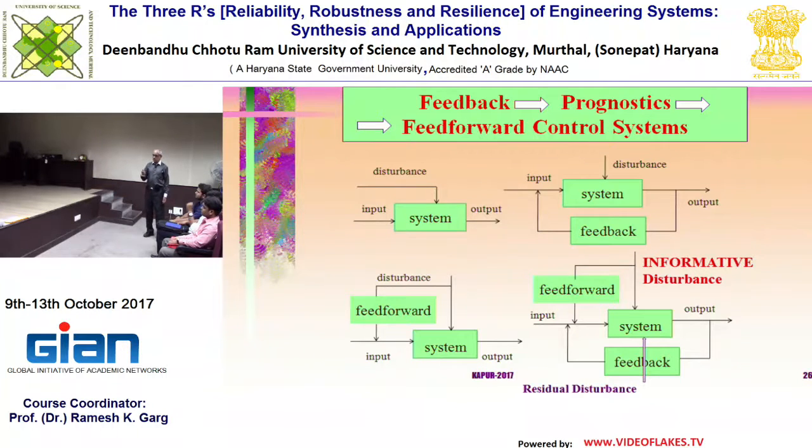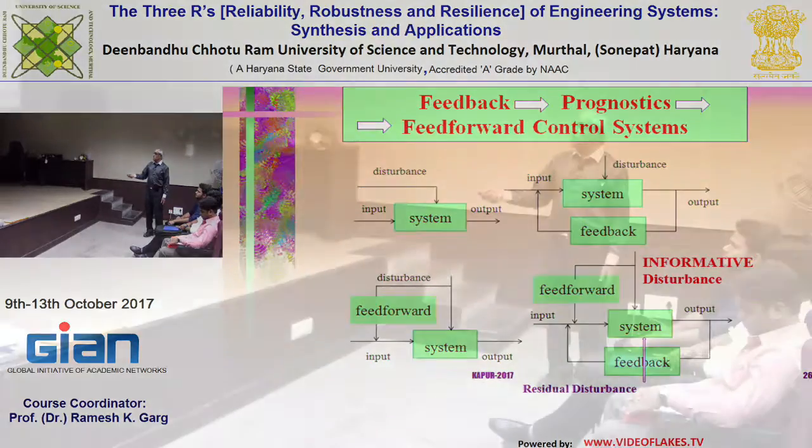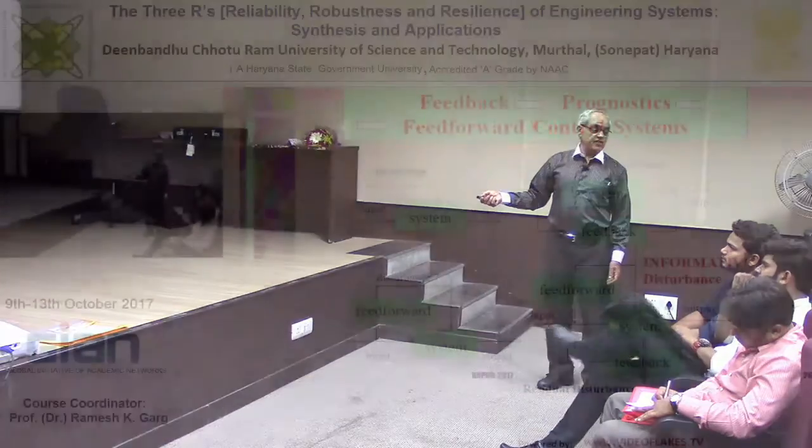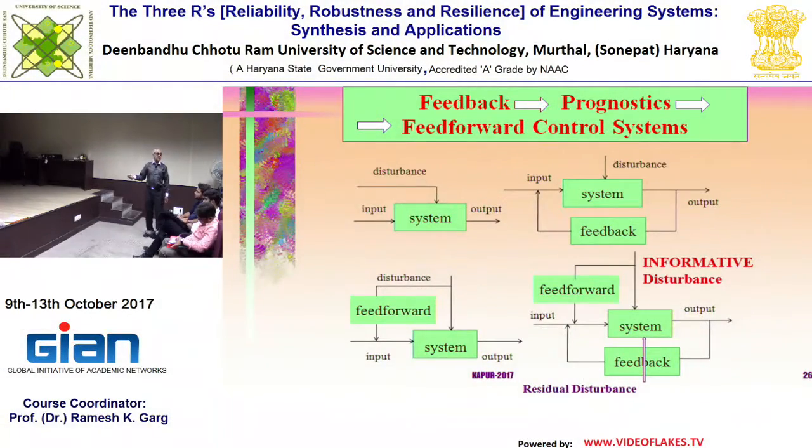In real life, nobody fully understands the system, so with this disturbance, many things are unknown or unknowable. For those things you could do feedback, but for many we have enough knowledge so we could do feed forward. As soon as the disturbance changes, I change the input so that I don't make any bad output.